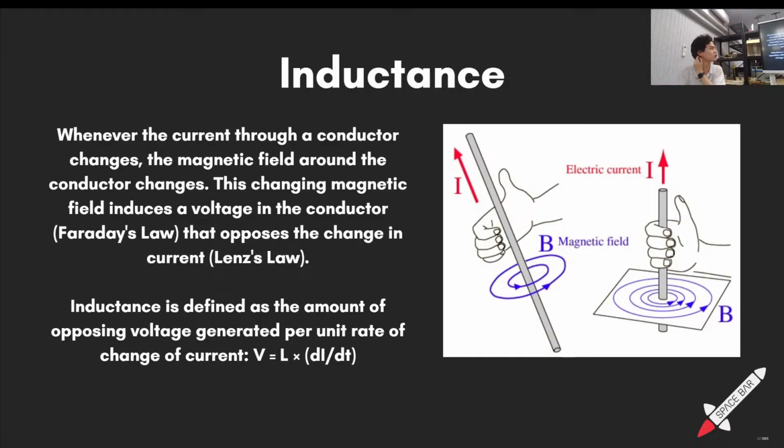I put the same picture because I couldn't find a good picture of inductance. I can just put a math equation there at best, so it's not worth it. Okay, any questions? Does the inductor just refer to the coil or wire, or can it be any conducting material near a circuit? You are absolutely right. It doesn't have to be a coil. Literally any wire will generate a magnetic field when you put current through it, and that magnetic field will change when the current changes, so it will have inductance.